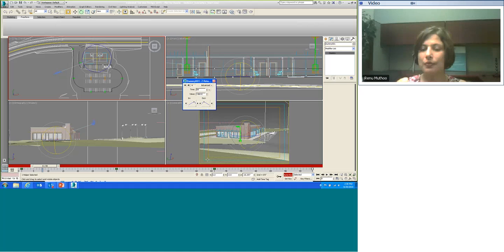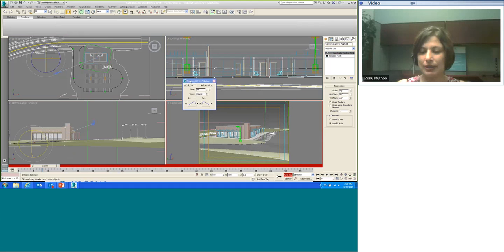There are two ways you can access the dialog box, either by right-clicking and selecting dummy Z, or you can just simply go into your dummy dialog box and move these small arrow buttons you see here. When you move this arrow, it moves to the third keyframe, this moves to the second keyframe, and this moves to the first keyframe. So we will set the linear interpolation for all the keyframes.